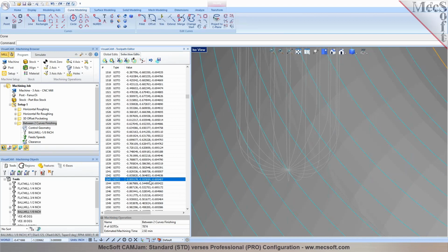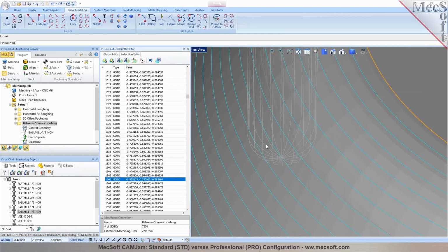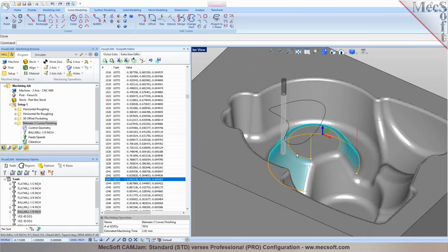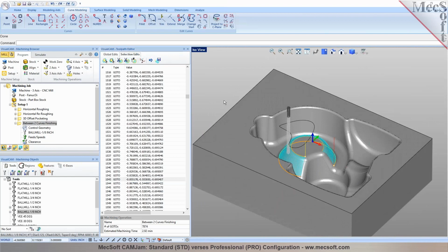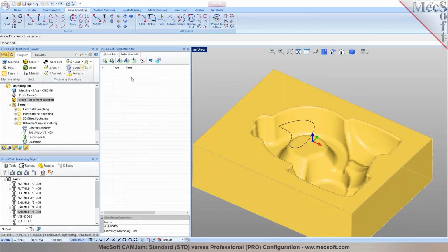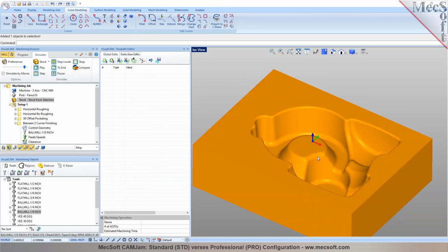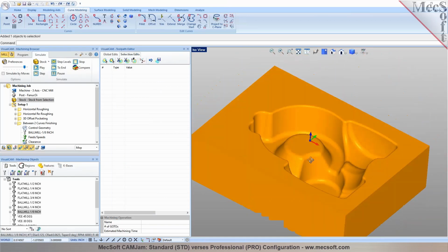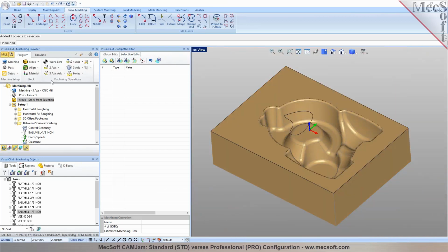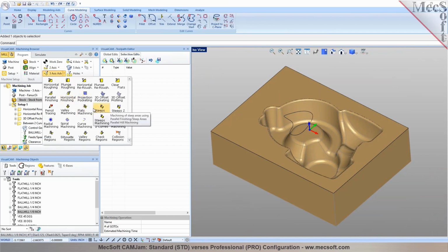There is a lot of features, absolutely. And you have more options under 3-axis machining. You can also do a stock by selection where, if you have an irregular shaped stock that you wanted to start out with, you can highlight it and do a stock by selection. So your stock is actually what you imported. Okay. And we have advanced 3D finishing methods like pencil tracing and remachining in here.